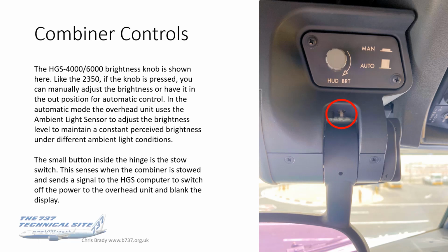There is a small button there inside the hinge. That's the stow switch. This senses when you've stowed away the combiner, and that will then switch off the power to the overhead unit and blank the display. So it's not heating up whilst the thing's not in use. Just saves life as well.